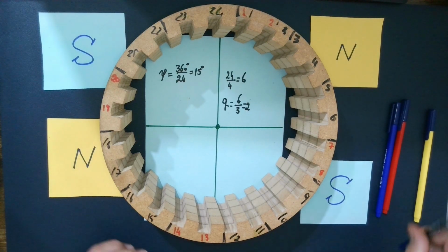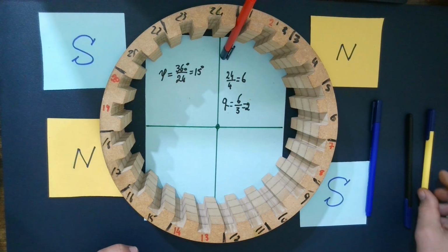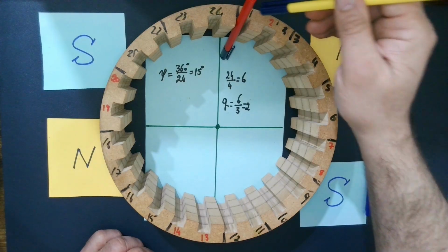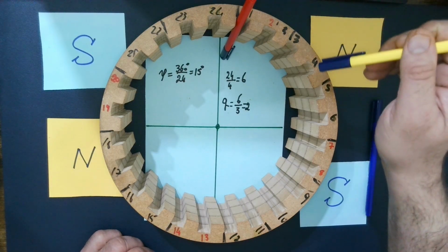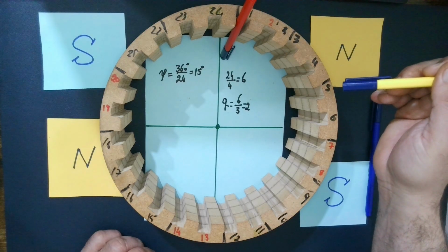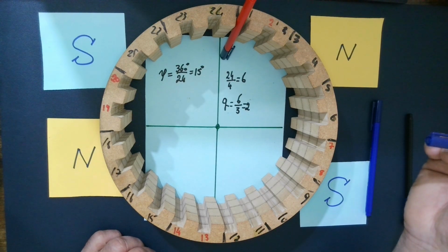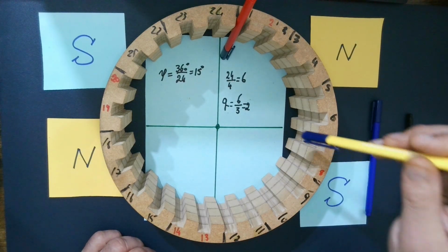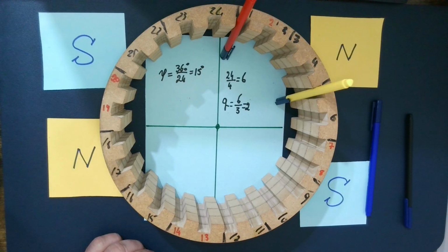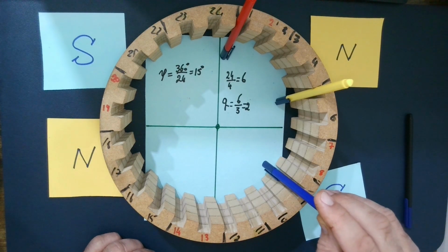So if we start phase A at slot number 1, so phase B will start after 120 degrees. So that one is 15, 30, 45, 60 degrees mechanical. Multiplied by 2, theta electric equal P over 2 theta mechanical. So theta electric equal 2 multiplied by 60, 120 degrees. So phase B starts at slot number 5. And then phase C is going to start at slot number 9.